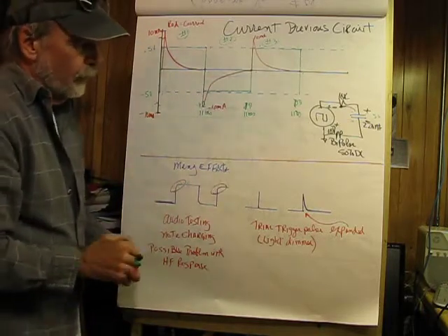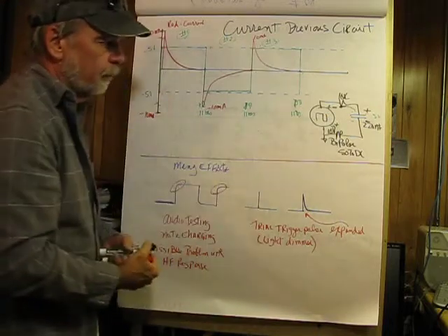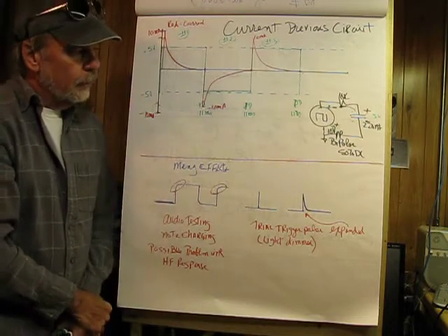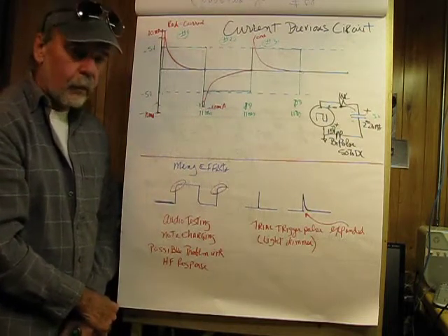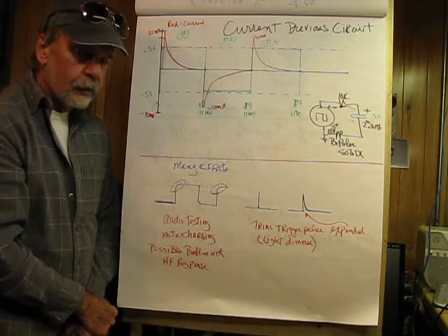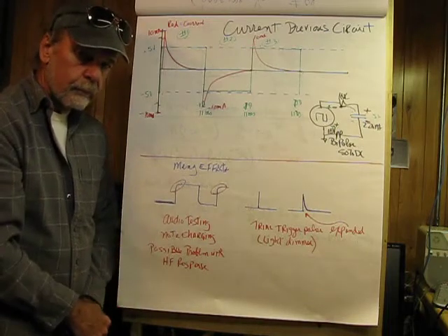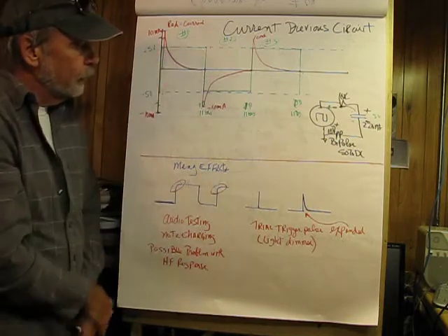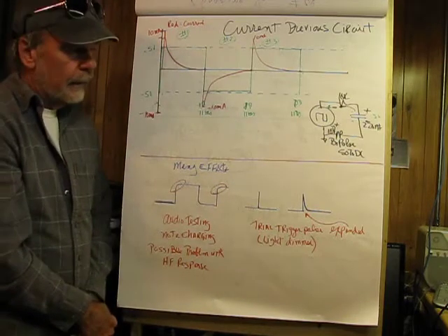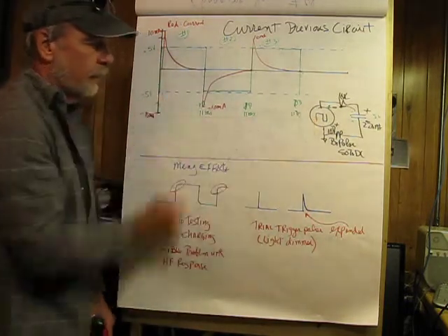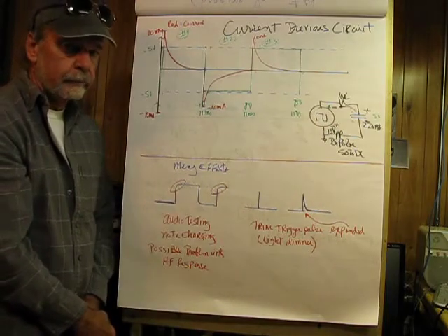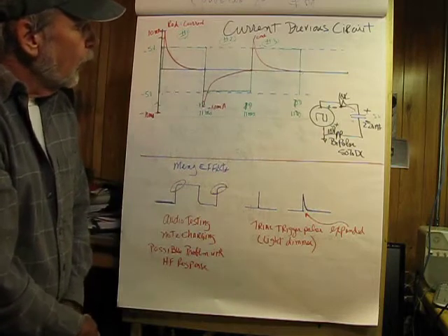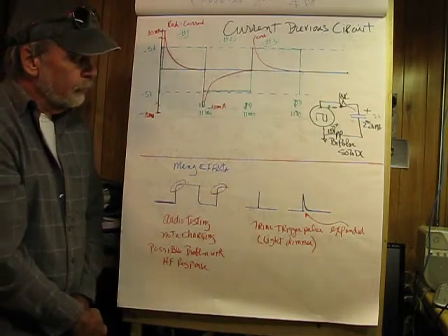So what this emphasizes at the transitions is the importance of adding voltages and understanding what's series aiding and series opposing. And that's the only way we're going to get correct answers when we look for current here. Now, if we get this wrong at a transition, the current's going to be 0. Obviously not correct. So that would be the current flowing from the previous circuit.